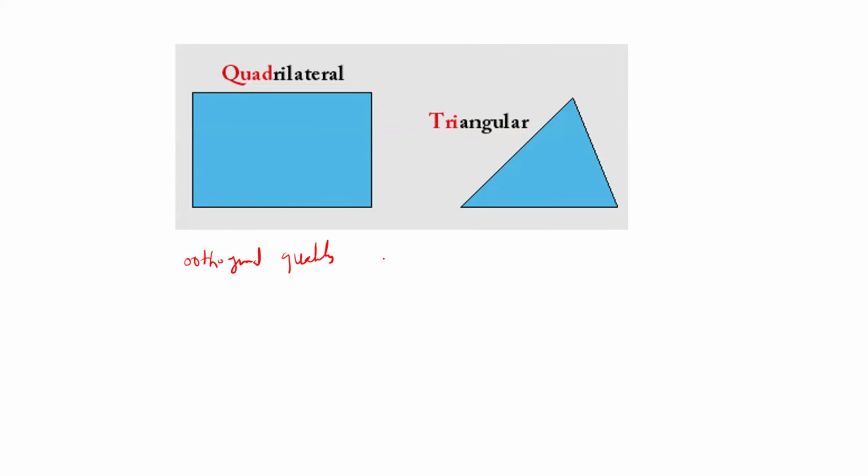at least should be not less than 0.01. So this is the minimum quality we should be having. This is defined by the Fluent manual. So this is the minimum quality that we should have in the mesh. Below this value, we cannot accept it, and this will also give you a warning in Fluent. So this is the minimum quality that we are requiring to have in the mesh.